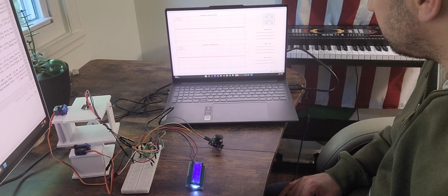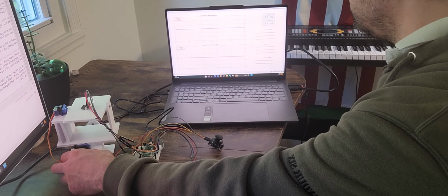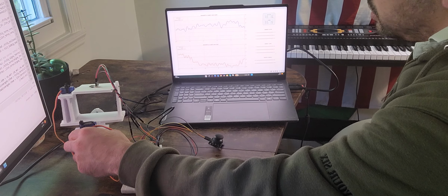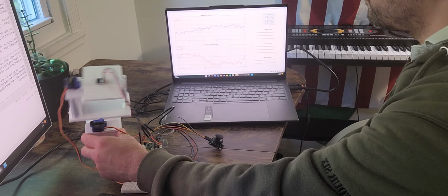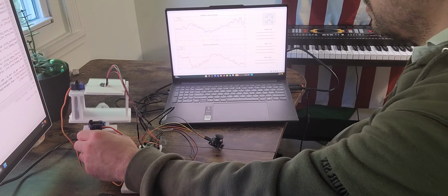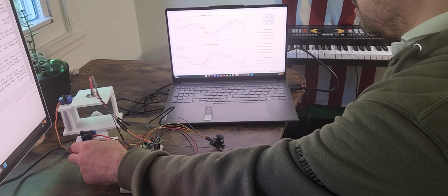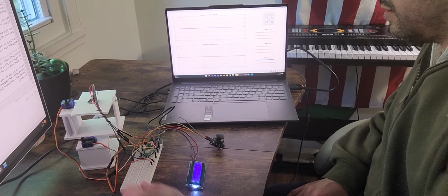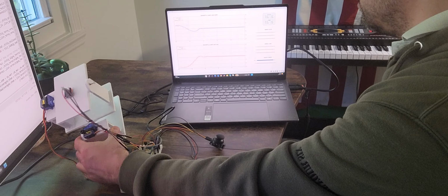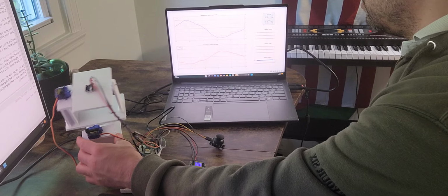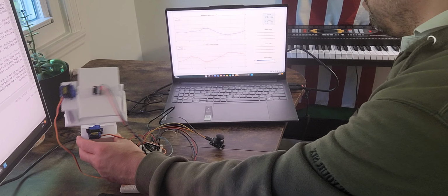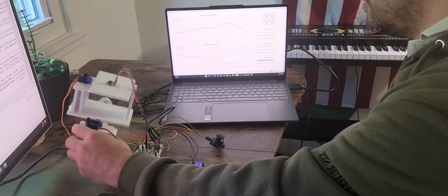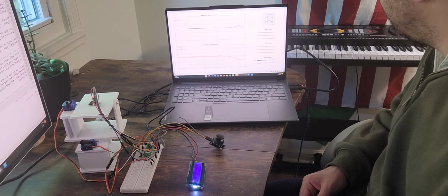If I put that, for example, to zero, I'm basically turning off the filter now. As you can see, all these disturbances, all this error, is just passing through, and that's why you have this unfiltered data coming through. And if you put the tau now to very high, now you'll basically overfilter it, right? Now you have a much smoother curve, but that also is not ideal because now you can get lag there. If it's too smooth, then you'll have some lag.